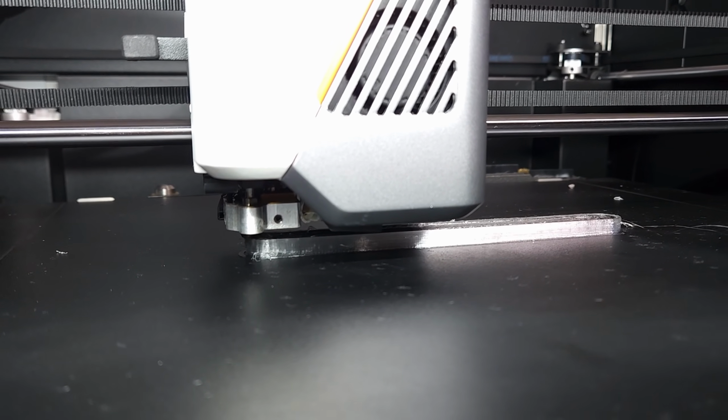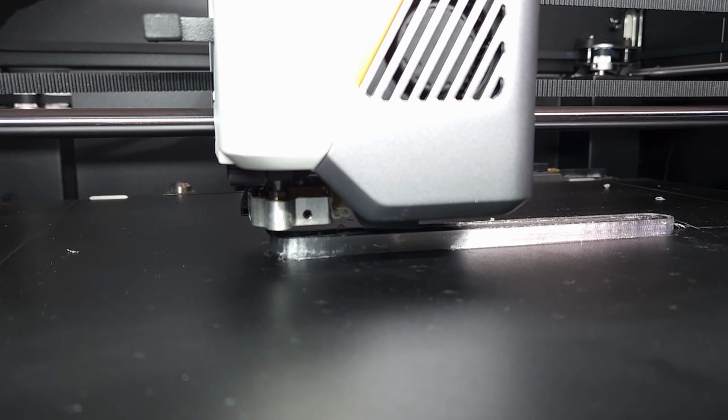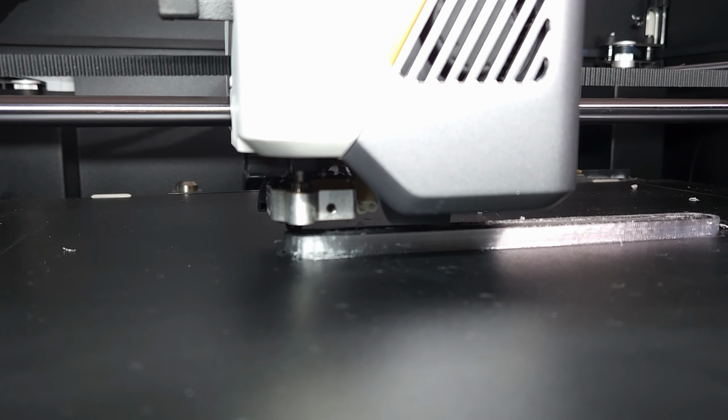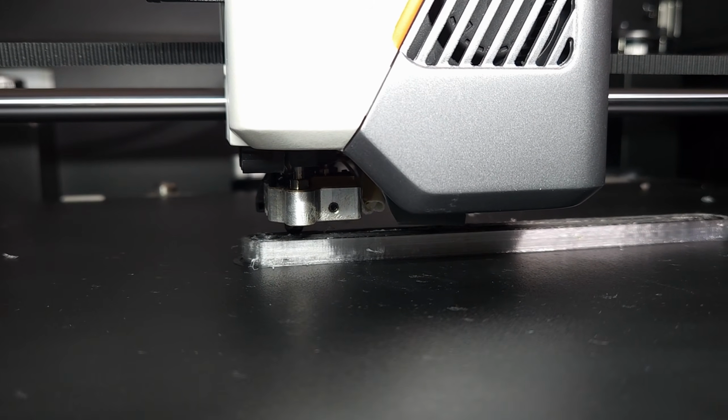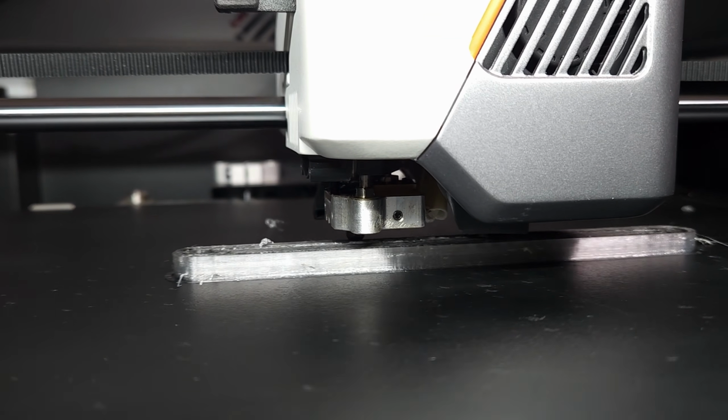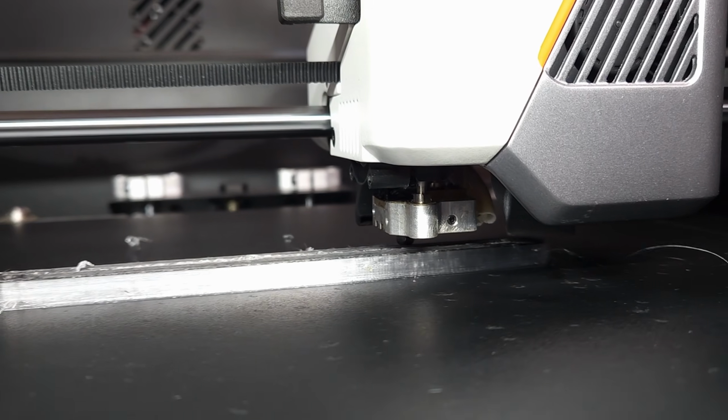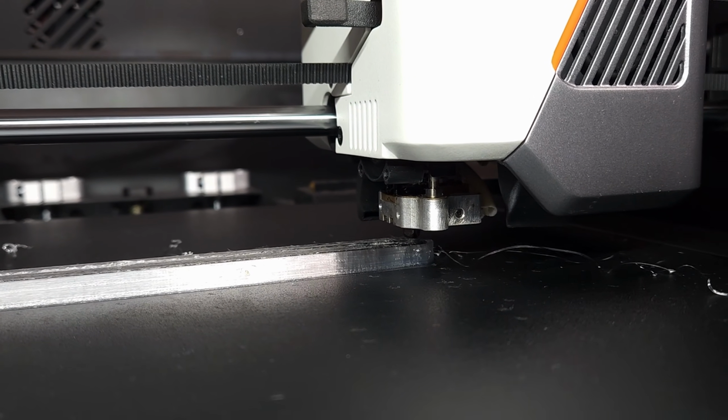This is obviously going to take quite a bit longer than it would on a normal 3D printer because it's laying down that continuous carbon fiber. One thing I've noticed is that it lays the continuous carbon fiber much more slowly in a curve than it does in a straight line. And that makes sense because it's having to be stuck down into the print. And as it goes around a curve, that sticking down is going to be more challenging.